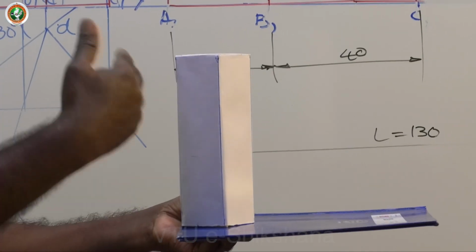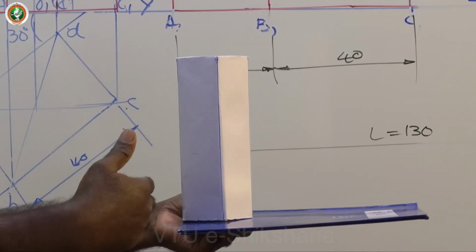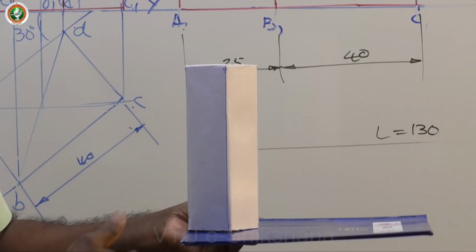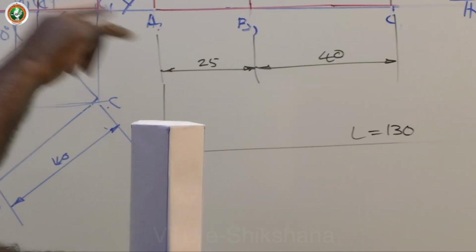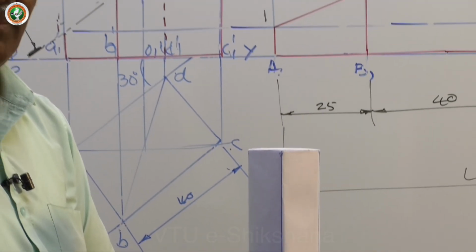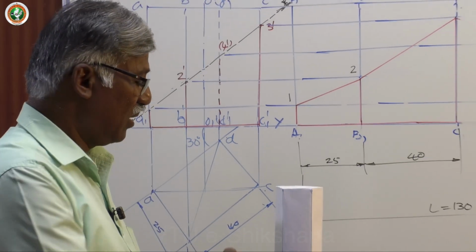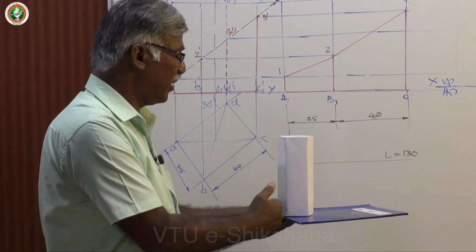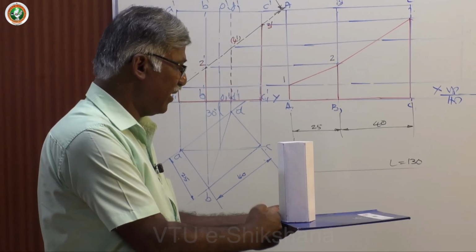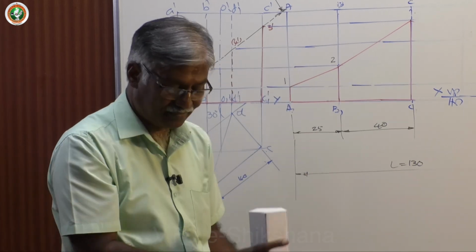Naturally the corresponding associated lateral face is perpendicular to VP. Now in this position you have to draw the figure, top view, front view, then consider the section plane. So I will repeat, this is the orientation. You must keep this line perpendicular to VP and start working.